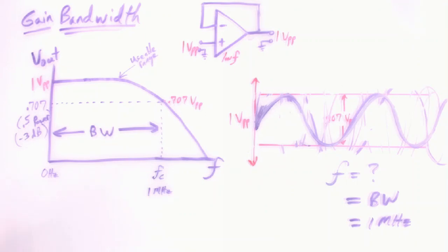I'll do a little chart here. Maybe that'll help us. If I wanted to build a circuit with a gain of 10, there would be a certain bandwidth that I can achieve with that circuit. If I wanted a gain of 100, I'll have to give up bandwidth to get to the gain of 100. My bandwidth will be 1/10 of what it was. So let me put a little chart together and we'll be able to stare at that.